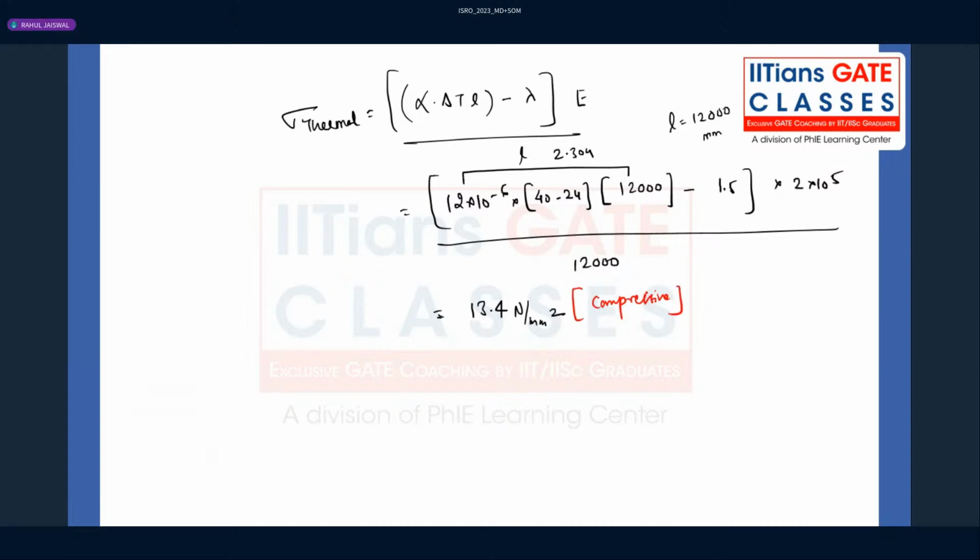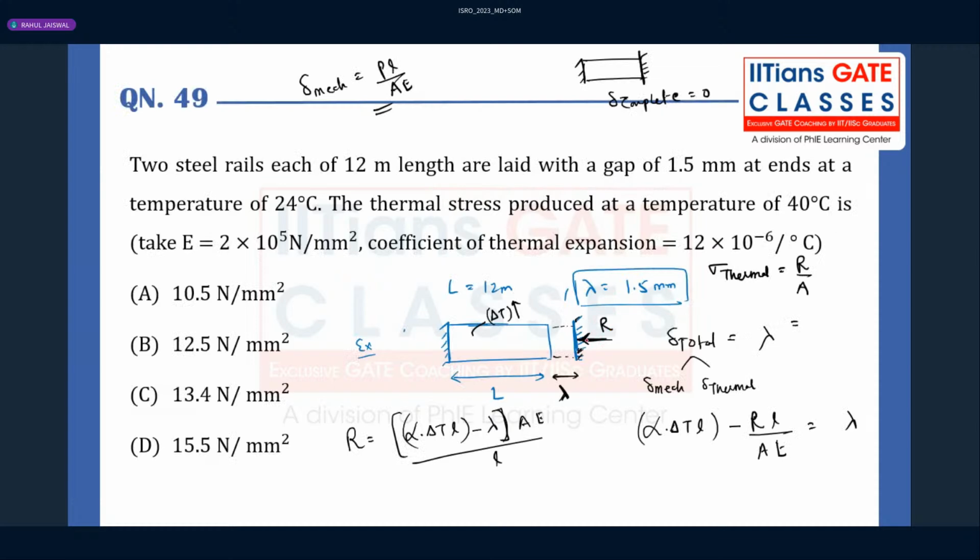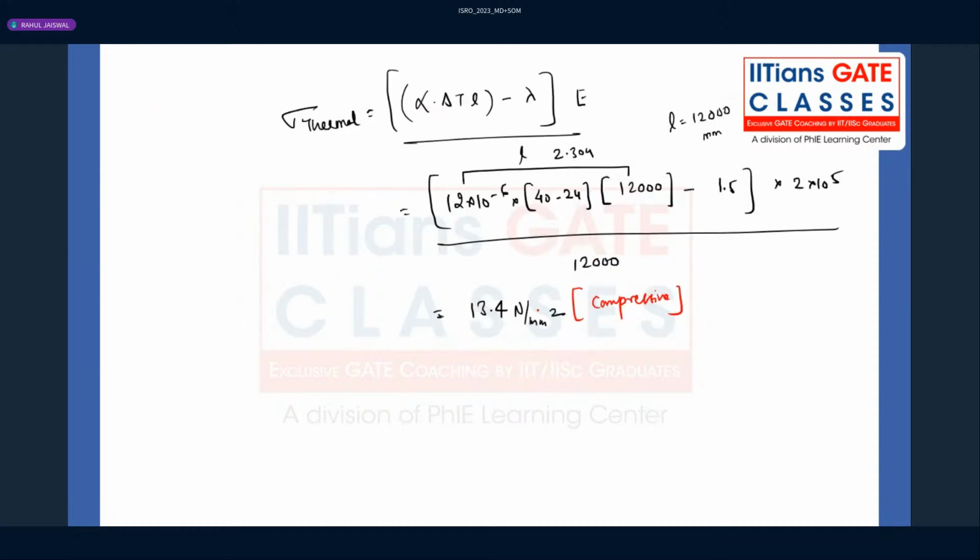How will you decide whether it is compressive or tensile? Because the reaction force is a compressive force offered by that support. When the temperature increases, compressive stress will be developed. When the temperature is reduced, then tensile stress will be developed.